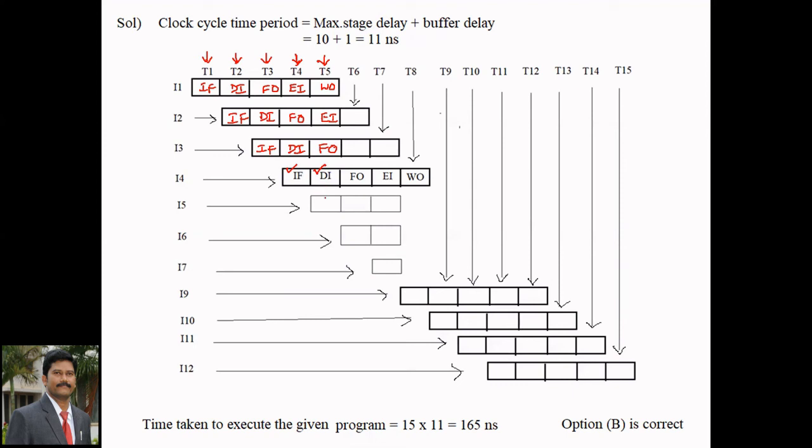At the same time instruction I5 enters. This is the branch instruction, but you don't know where it has to jump. Actually it has to jump to here. The jump should be taken from I4 to this one, but you don't know the target address until its execution.